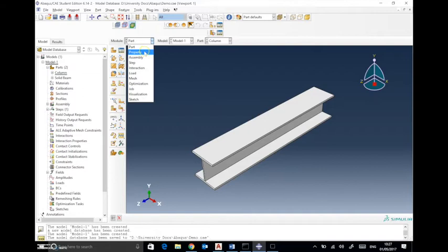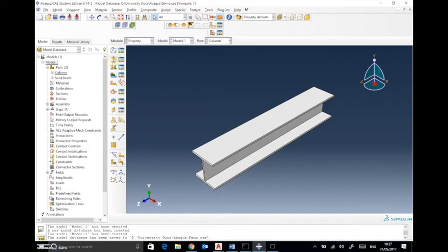So we have to carry out all these steps, and for the optimization and the sketch we're not gonna look at them. For the property, we need to create a material and then create a section and assign. The third and last step is assigning that section to the elements that we have.